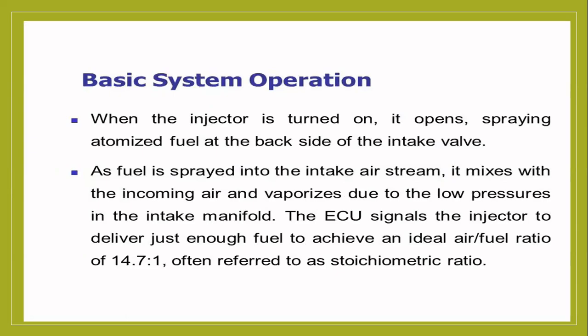This is also important. When the injector is turned on, it opens, spraying atomized fuel at the backside of the intake valve. So don't spray through the intake valve, okay.